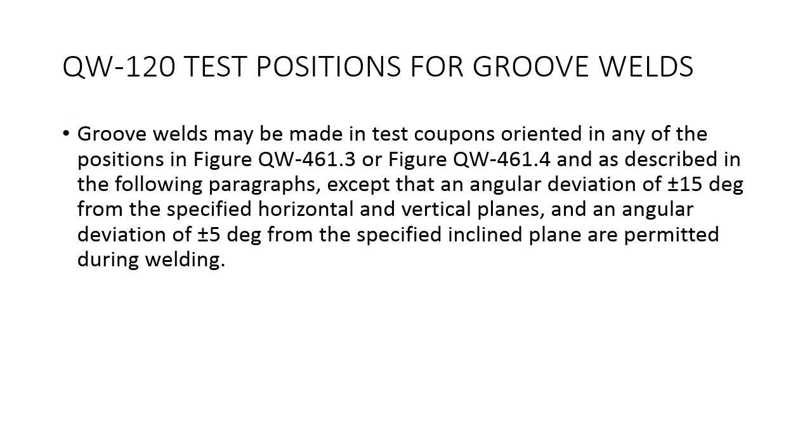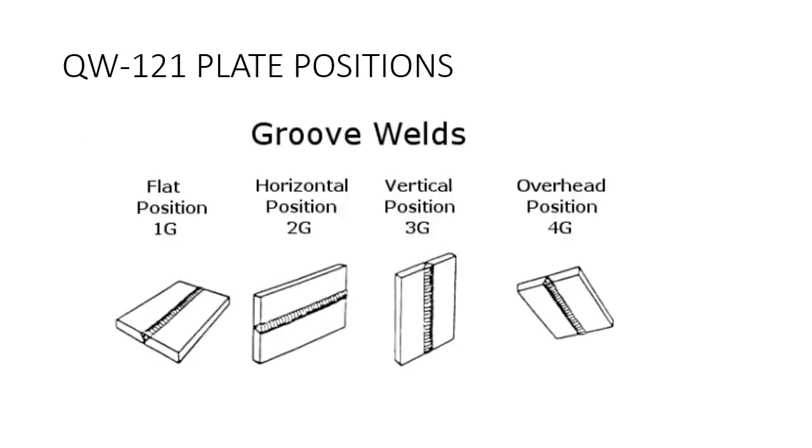Here's kind of the bedrock foundation of the language that we're going to be speaking, some of the terminology. And test positions is one of the cornerstones of this welding code as far as lingo you're going to need. QW-121, plate positions. Like I said, this is pretty important stuff. If you can't talk this language about weld positions, you're going to sound like you don't know what you're doing. You could be a pretty sharp person, but if you can't speak the welding language and talk in the context of the codes and plate positions.